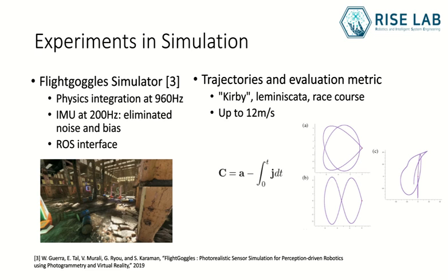In order to verify this model, we use the Flightmare simulator, which provides IMU measurements at 200 Hz. In these experiments, we eliminated the noise and bias, since it is possible to compute those values in other algorithms, using other algorithms like visual inertial odometry.